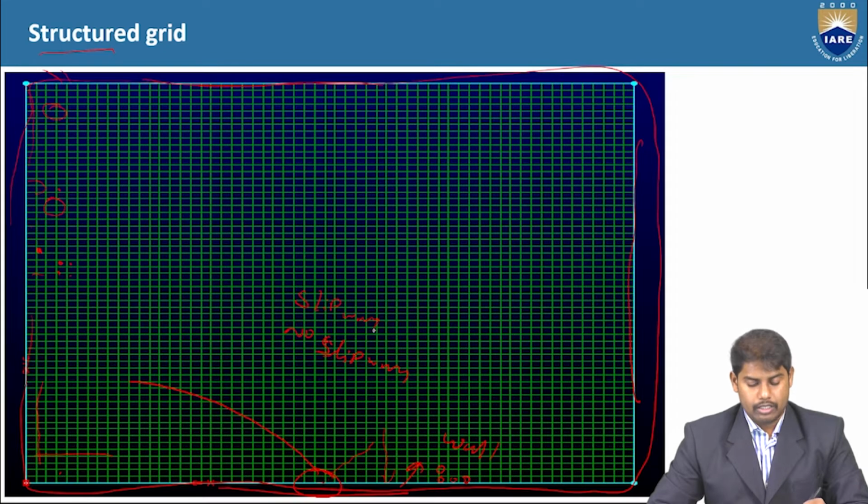The first fluid particle near the wall will have zero velocity. The next fluid particle will have some velocity, and likewise the other fluid particles will have increasing velocity. Because of the viscous phenomena and the viscosity effects present near the wall, the first fluid particle will stick to the surface. This condition is nothing but a no slip condition.